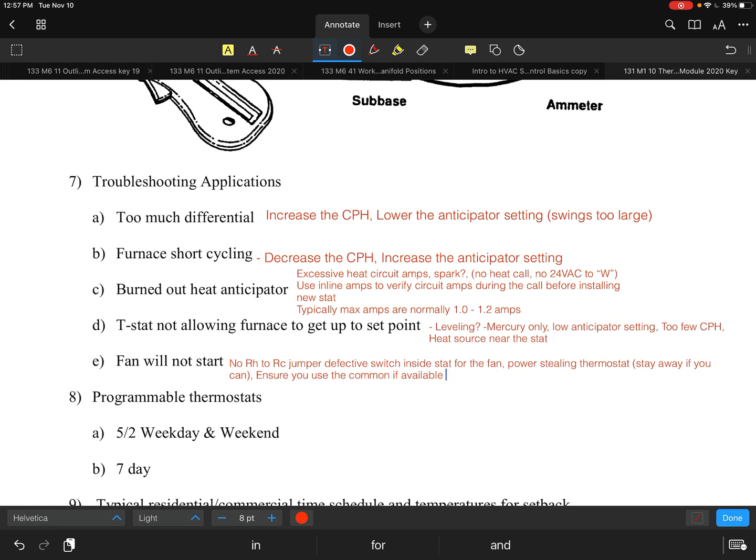So certainly, if I don't have a heating call, what's it going to do? I'd be looking at, all right, is the thermostat programmed correctly? Is it wired correctly? And obviously you eliminate all these issues. So I think the note that I would just put on there is, ensure, I would say, wired correctly is certainly one of them in any application.